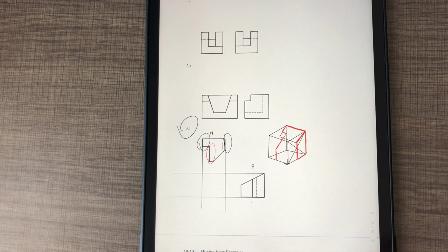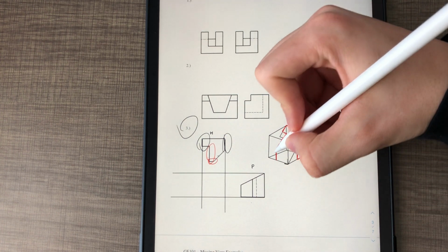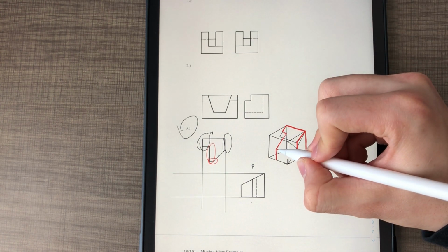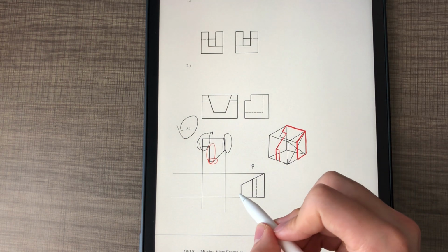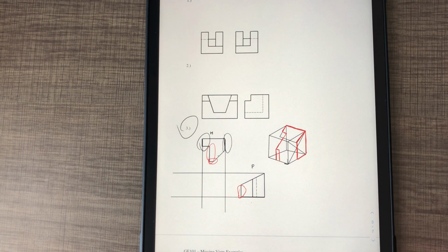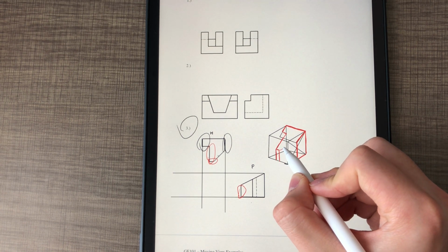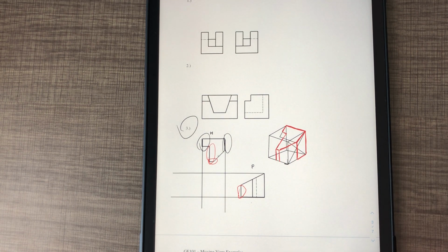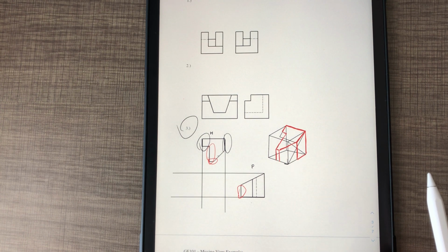Are you seeing it start to take shape now? Well, maybe, maybe not. We can actually bring this dimension over now. So on that front face, I'll bring over that dimension parallel. And then, of course, downward, because I know from the side, it's got to look like this. And now, I can complete that top view. So does this correspond to this? Yes, it does.